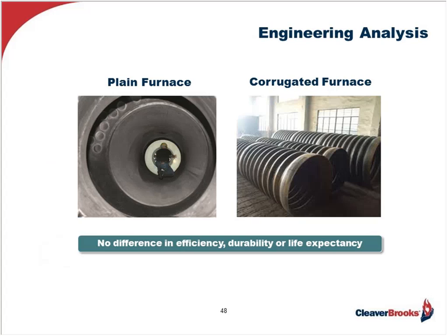And then the construction relative to the weld attachment furnace to tube sheet is another criteria. The tube sheet to the shell, and then the ligament distances between the tubes mounted within the tube sheets themselves. Those are the differences that cause either the plain or the corrugated to fail. It's not the design of the plain or corrugated, it's how they're attached. Okay? However, the real reason for using corrugated versus a plain furnace is a combination of economics and design integrity.